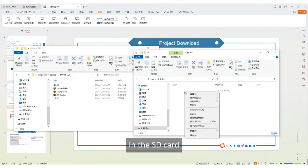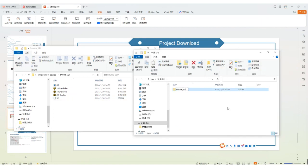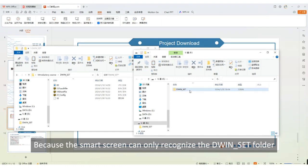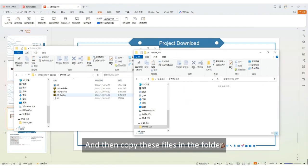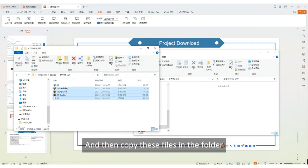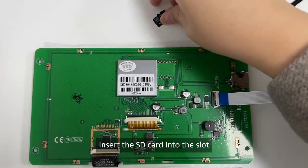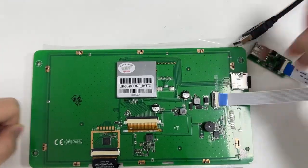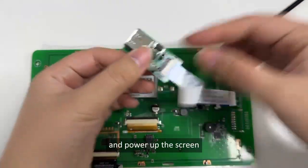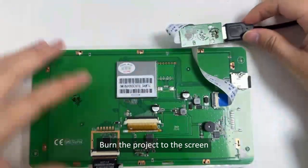In the SD card, create a folder named DWIN_set, because the Smart Screen can only recognize the DWIN_set folder. And then copy these files in the folder. Next, insert the SD card into the slot. And power up the screen. Burn the project to the screen.